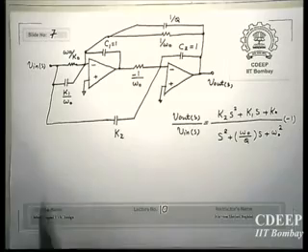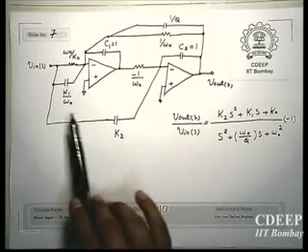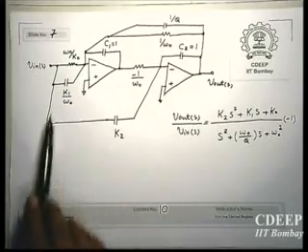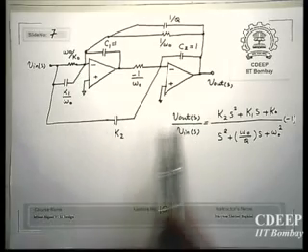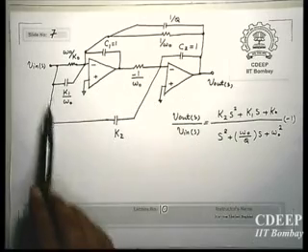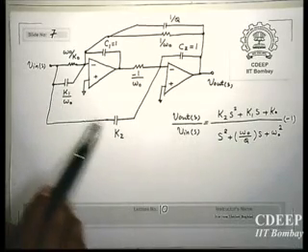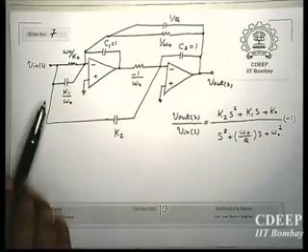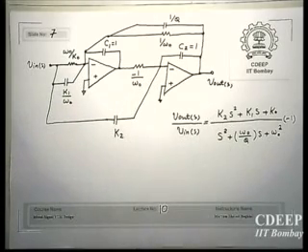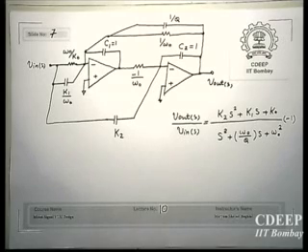See, as you notice, putting two capacitors from input to output in the path, in the summing path. See, this is at the summing point. This here you will write KCL when you draw SFG. In fact, you can draw now SFG for continuous time also, similarly. So K2 and K1 are in fact dependent on the value of these two capacitors which are in the direct path from input to summing point. That's why it adds 0. And of course, in contribution with this resistor. Otherwise, one of your zeros will be at S equal to 0.